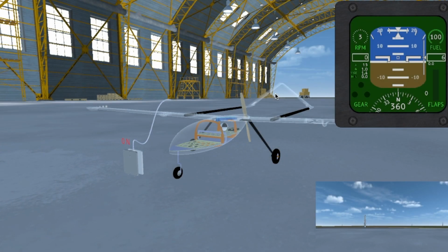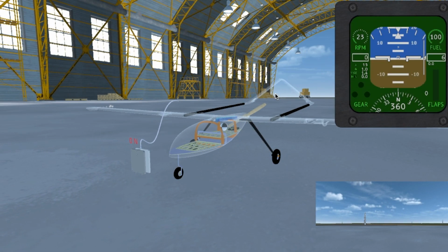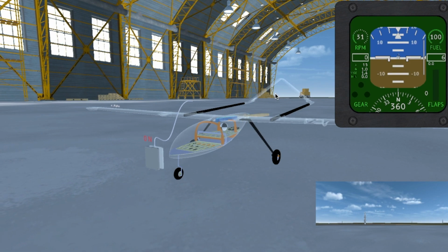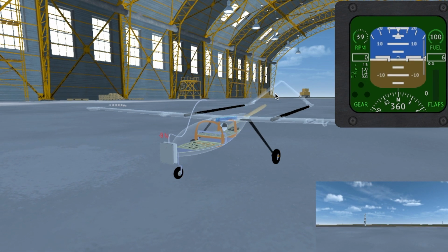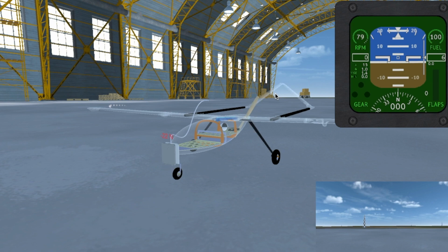Next, we will proceed to the thrust test. Following the weight and balance test, a thrust test was conducted to determine the linear relationship between RPM and sea level thrust. This information can be referred to by the pilot during a mission, such as during takeoff. The maximum sea level thrust achieved was 28 newtons, and the relationship can be viewed in the accompanying graph.